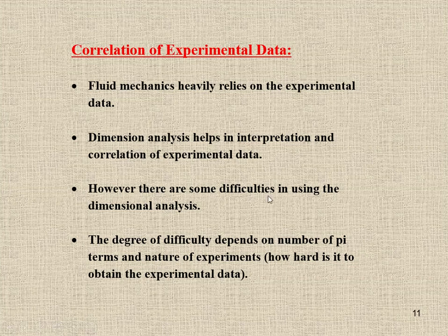However, there are some difficulties in using dimension analysis. Dimension analysis does not give you any equation. If you have six variables in a problem, it reduces the number of variables, so it reduces your effort in the experimental analysis. But it does not give you an empirical relationship like y equals mx plus c.